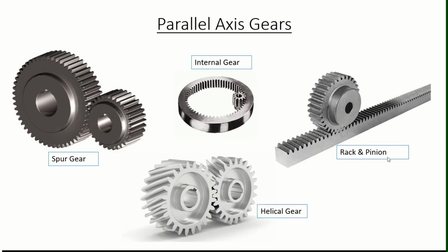So basically what it is doing is converting a rotational motion into the translational or the linear motions. These gear racks can be divided into straight tooth racks and also the helical tooth racks, but both have the straight tooth lines. By machining the ends of the gear racks, it's possible to connect these gear racks end to end as well.